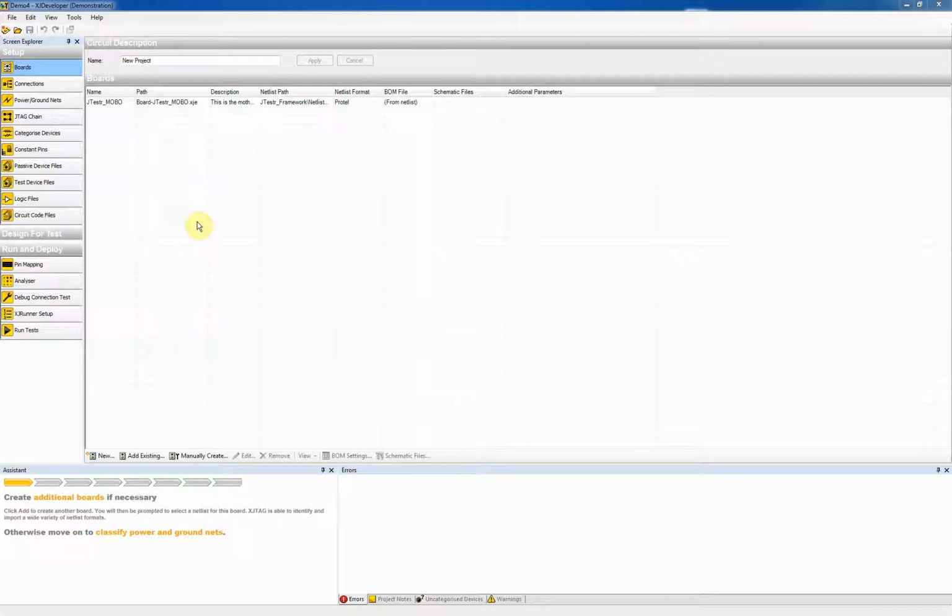This video is a continuation from the Demo4 video where we added an ADC DAC card to slot 6 of the J-Testr system. In this video we will add a JTAG I/O card. As the name suggests, the JTAG I/O card is a JTAG bus device. The previous two videos have shown the addition of system bus devices. The I/O card will be fitted to slot 4, which is on bank 1 of the motherboard peripherals.